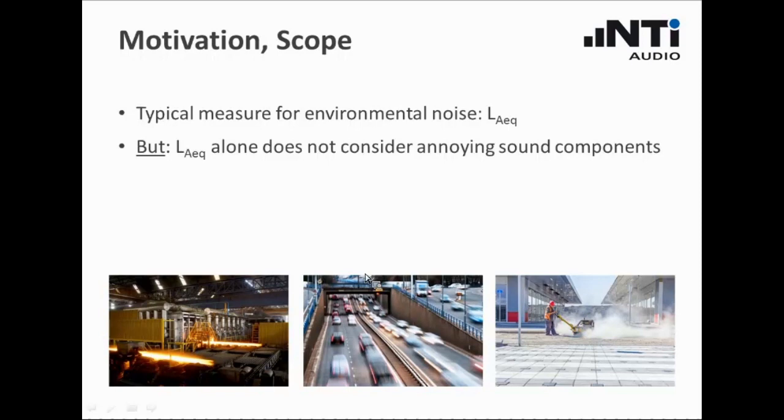You may have a certain LAeq which sounds quite acceptable, and you can have another environmental noise with the same LAeq, but that is highly annoying, highly disturbing. So what we need is a measure to rate this annoyance, and that is called the rating level.